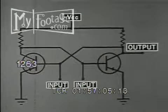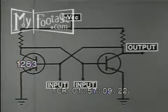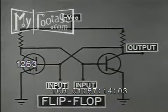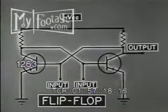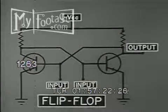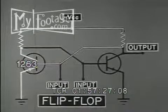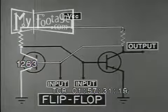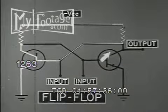This common computer circuit is also a basic switching circuit. It is a trigger circuit, commonly called a flip-flop. It's a simple arrangement of two switches with their bases and collectors cross-connected. Only one switch functions at a time. It gets its emitter to base forward bias from the reverse bias on the collector of the other transistor.